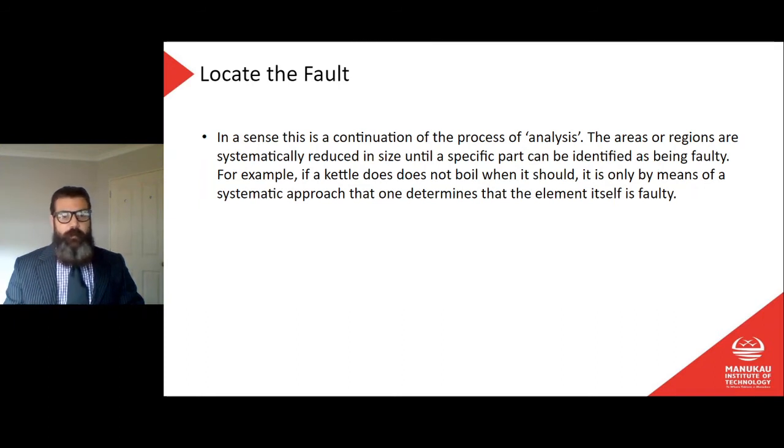where that fault is. Again, going randomly is probably not going to help you. If I do that test and then I go, okay, it's on this circuit, and then I just go to the first thing on that circuit, disconnect everything and retest. Okay, well, it's still further down the circuit. Well, I go to the next part of the circuit, disconnect everything.